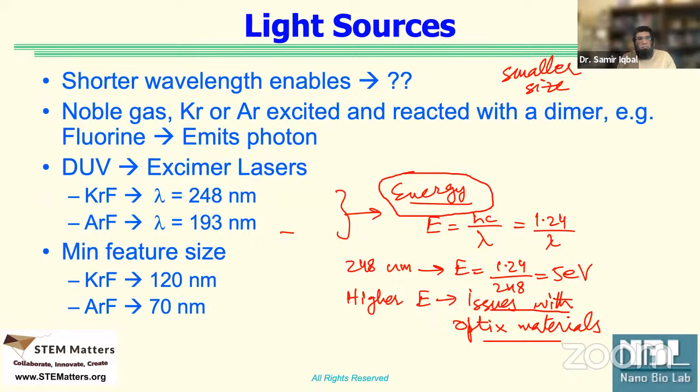There were three important criteria: minimum feature size, how small; pitch, how close can we make things; and depth of focus, how much topographical difference in height there can be. When we are talking about multi-layered device characteristics, we want to stay in focus as much as we can.